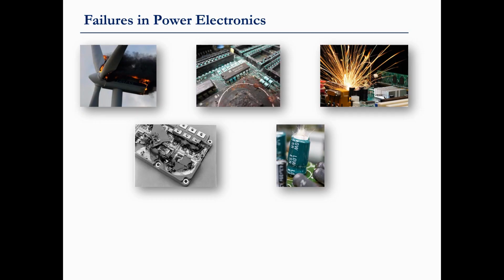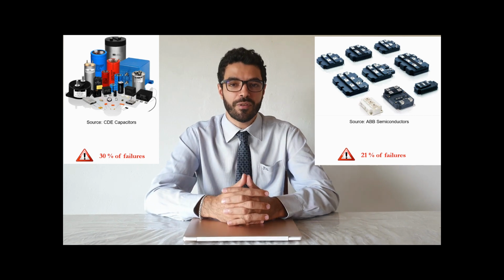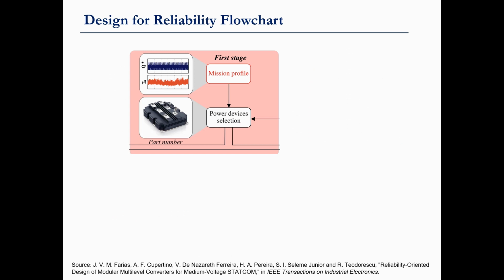The failures in power electronics components can be classified in wear-out and random failures. Semiconductors and capacitors are responsible for an important percentage of failures. To deal with the components wear-out, I proposed a reliability-oriented design for an MMC-based STATCOM. The design inputs are the converter ratings, the operating mission profile, and the reliability target.